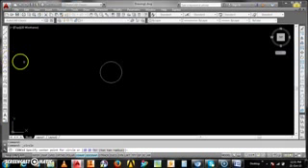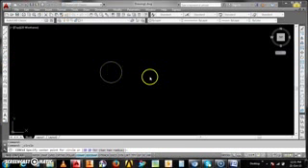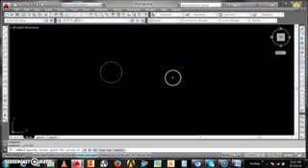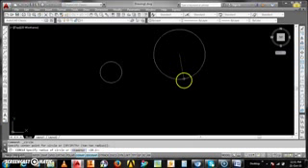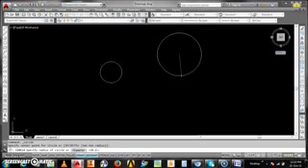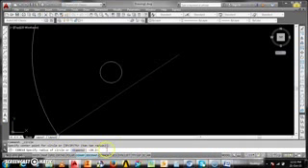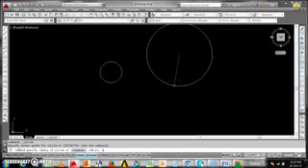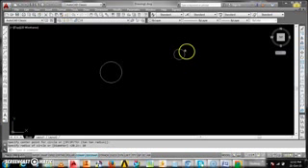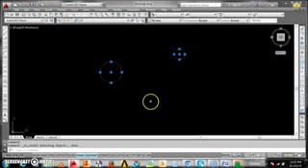Suppose I have again selected the circle. First you have to specify the center point, then you have to specify the radius of the circle. What radius do I want? I want 10 radius, 10, enter. So this circle is of radius 10. Okay, so I will delete all: Control plus A to select all and then delete. Slowly we will learn each and everything.